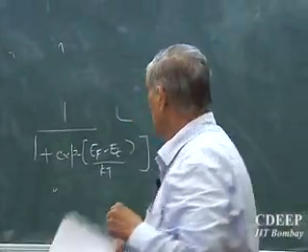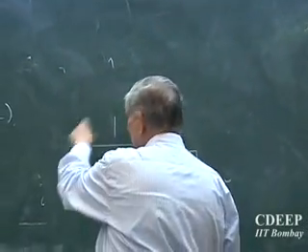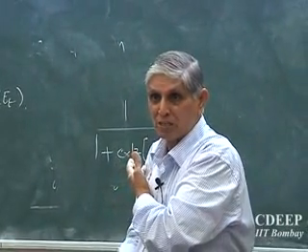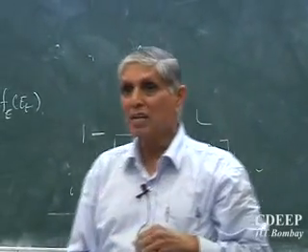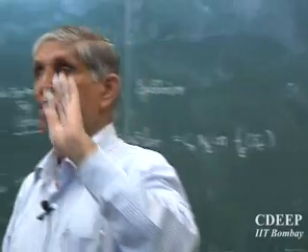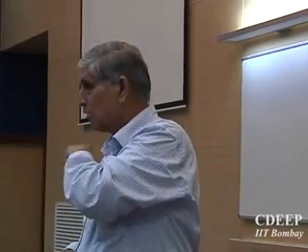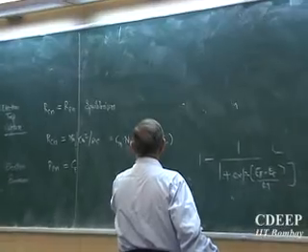Now this is not actually that FT. This is the distribution function, the possibility of occupancy. But how many are available? How much should actually be evaluated? These are the empty ones. If the probability says occupied, how many are empty? 1 minus FT is what we should write there. Instead of FT, it should be 1 minus FT. Is that point clear? This is not correct.